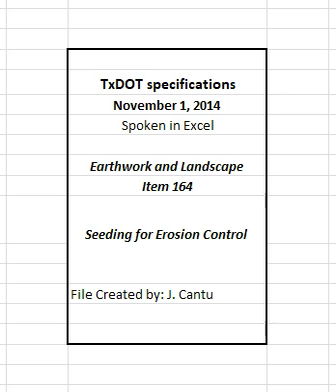When buffalo grass is specified, use seed that is treated with KNO3, potassium nitrate, to overcome dormancy. Use Tables 1 to 4 to determine the appropriate seed mix and rates as specified on the plans. If a plant species is not available from the producers, the other plant species in the recommended seed mixture will be increased proportionally by the PLS per acre of the missing plant species.